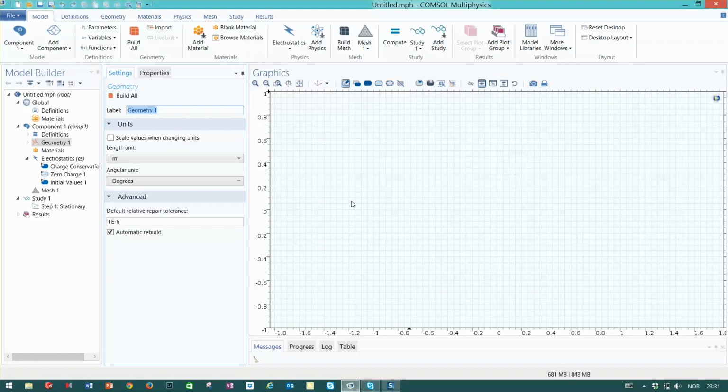We know now that small elements make more accurate solutions if we don't make a mistake in any way, and we should use more of a coarse mesh at other places just to save computation time. So very often we will see a big variation in element size from the biggest to the smallest.